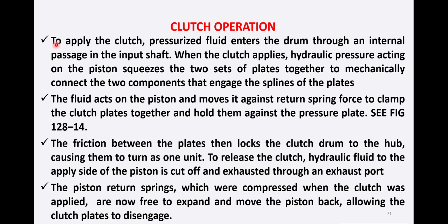Now, clutch operation. To apply the clutch, pressurized fluid enters the drum through internal passages in the input shaft. When the clutch applies, hydraulic pressure acting on the piston squeezes the two sets of plates together to mechanically connect the two components that engage the splines of the plates.